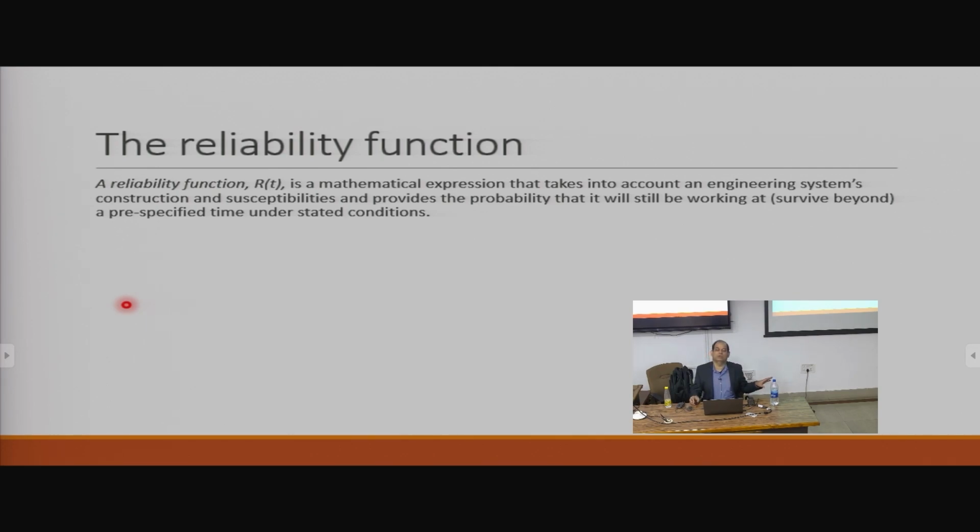So when you have, let's say, a hydrokinetic turbine working in a river, you will look at the input stream velocity as a stochastic process, okay? In which case, you will solve the stress-strain relationships using the velocity as one of the inputs, and from that, you can get to the stress generated and then whether it will fail, okay? So in those cases, we explicitly consider the system susceptibility and find the probability of failure because we have a model of uncertainty, which is the stochastic process that the velocity or any other input follows.